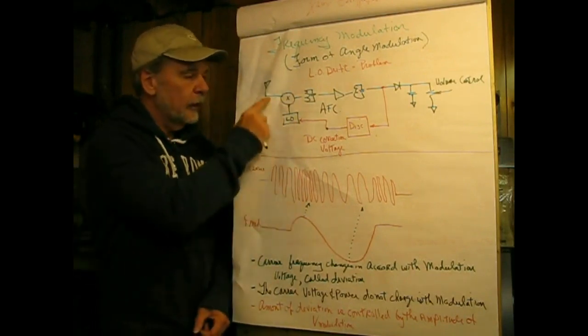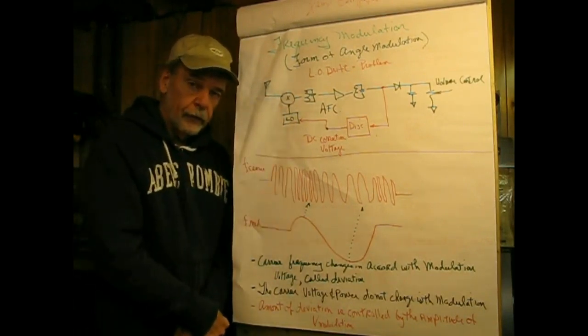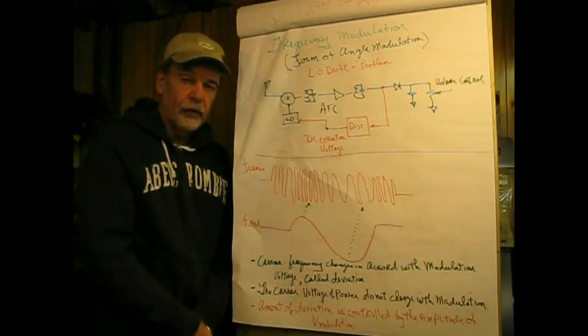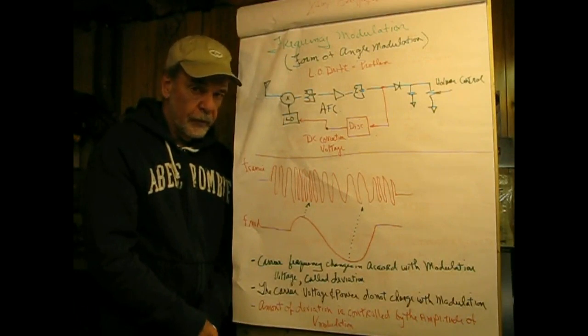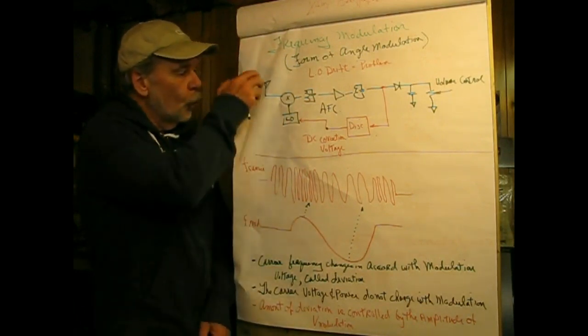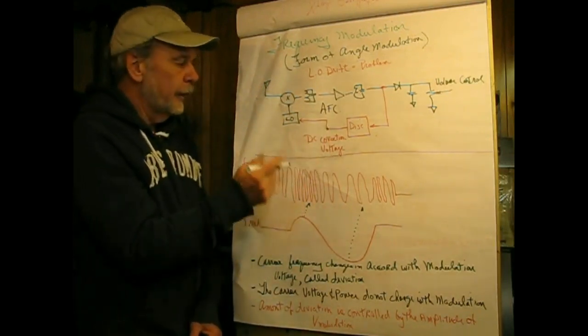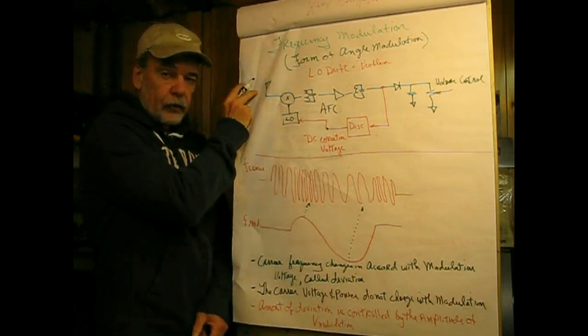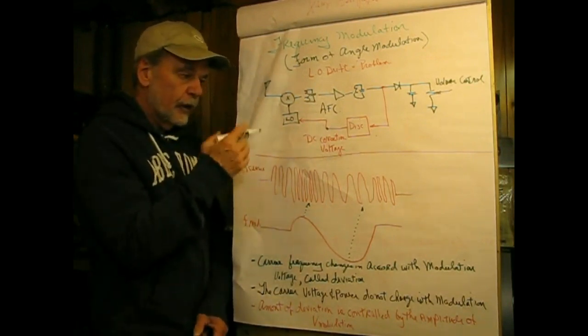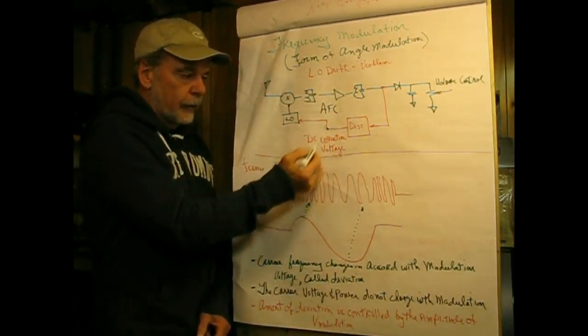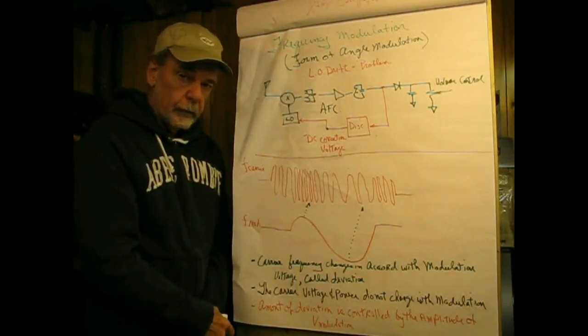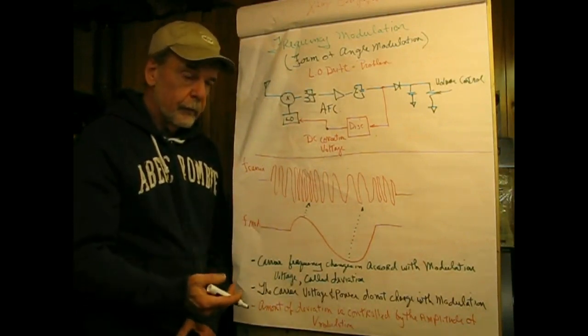Now, the incoming frequency by FCC standards for a standard AM broadcast station is allowed plus or minus 10 hertz to be in specification, so that's pretty tight. Anyway, wiggling this here would produce a correction voltage, and what was noted is that if you change the incoming frequency, say in a sinusoidal manner, the correction voltage would also exhibit a sinusoidal behavior.